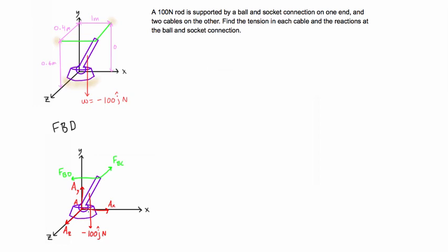You'll notice that these are just like force reactions. We have AX, AY, and AZ. That's because of the ball and socket joint, as we talked about in the previous videos. The ball and socket, because this is fixed to the ground, prevents it from translating if you apply a force in any of these given directions. But it doesn't provide any couple reactions.